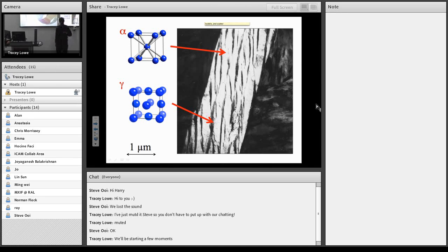Now, how is this relevant to the hydrogen issue? Well, I pointed out to you that diffusion of hydrogen through austenite is incredibly difficult. So supposing you have some sort of mechanism of hydrogen getting into the steel, like corrosion, but you have these continuous layers of austenite, then you may not actually be able to absorb that hydrogen. It's like a barrier, a diffusion barrier. And the work that I'm going to show you is not really on this steel where you have a 1/4 micrometer thick plates.